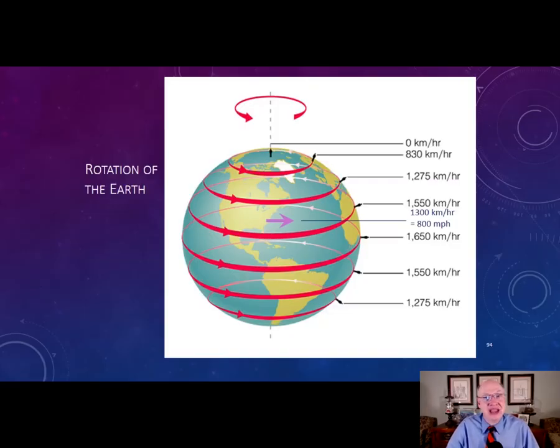Now, the European Space Agency didn't have the same national security concerns, and so the European Space Agency built their launch facility on the east coast of South America in French Guiana. They operate a large launch site in French Guiana, right there in South America, located right on the equator. And so for a given size rocket, they can launch a slightly heavier payload to orbit because they're moving a little bit faster than they would be in Florida. They're moving a lot faster than they would be in Europe, because Europe is so far north.